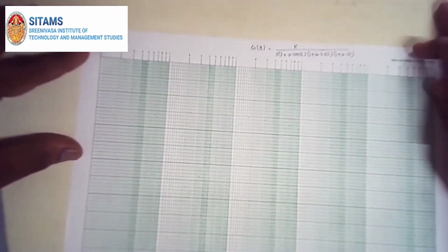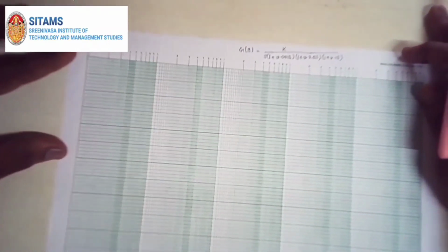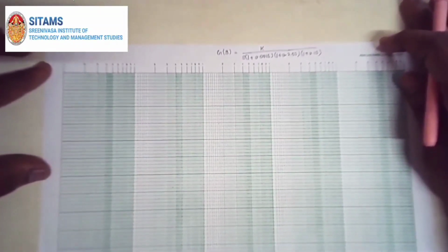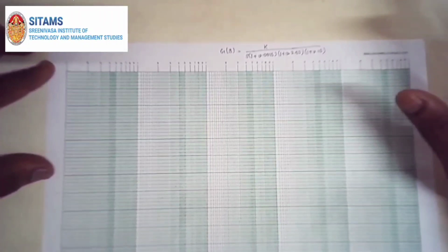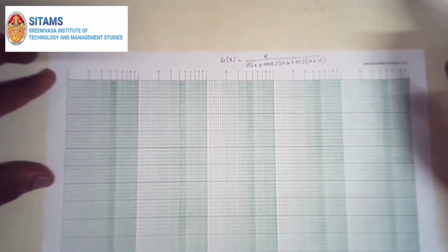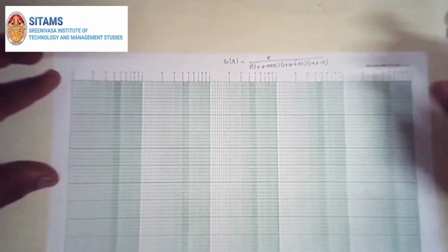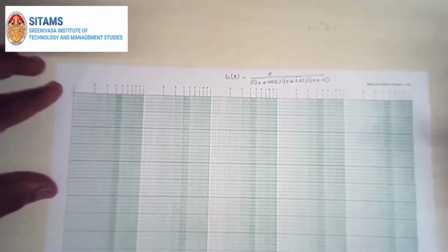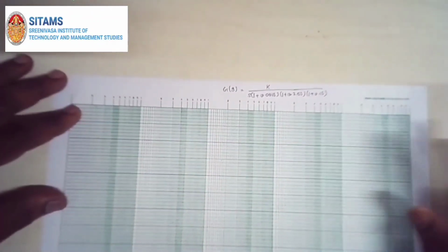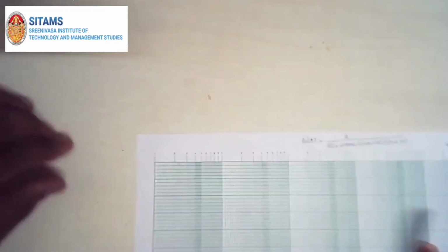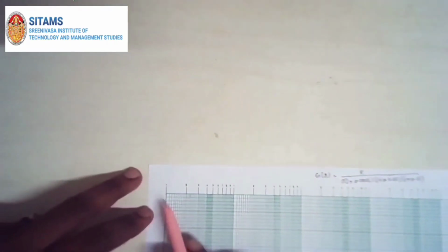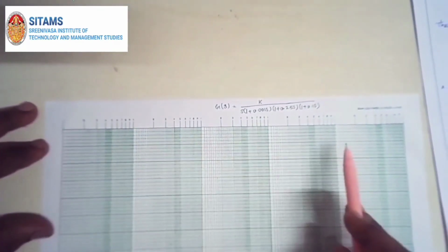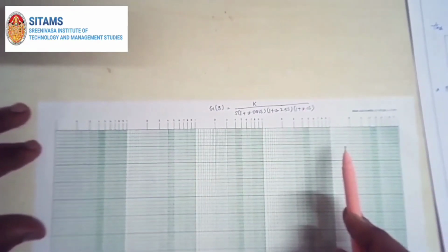So I have the coordinates of magnitude plot and phase plot readily available. In this video, we are going to see how we are going to sketch the plot, and from the plot how we are going to determine various parameters like phase crossover frequency, gain crossover frequency, phase margin and gain margin. So once you have taken the similar graph sheet, you can notice there are few sections of readings available along the x scale. So x scale here it is logarithmic scale.